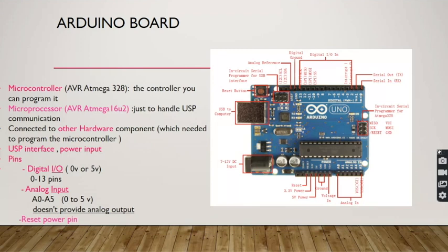In the theoretical lecture, I mentioned that the software consists of a firmware and the program the user writes. The user cannot change or modify the firmware, but sometimes the user needs to upgrade it. How can we do that? We can change or upgrade the firmware of this processor by using these pins.